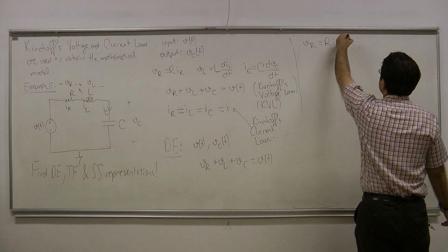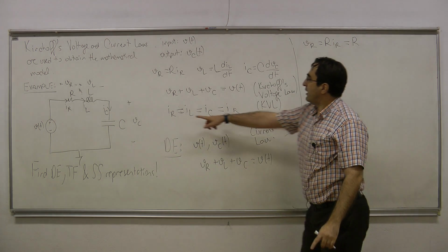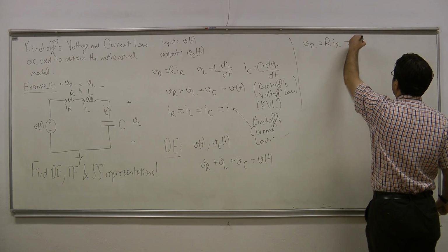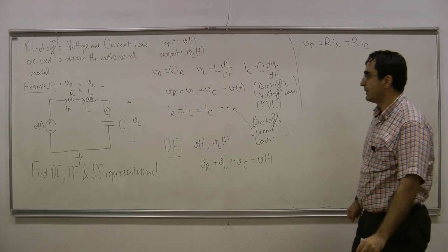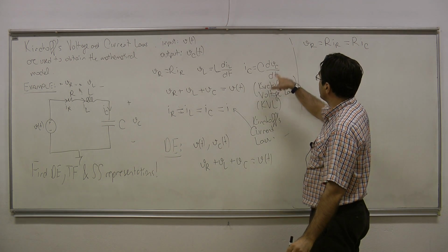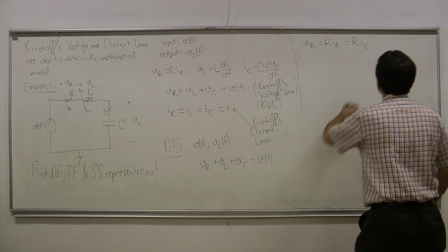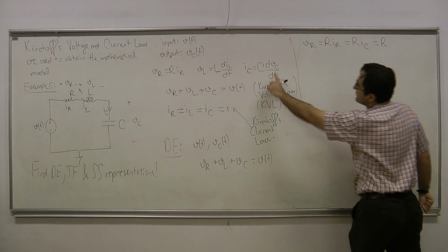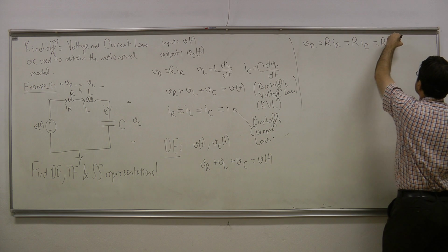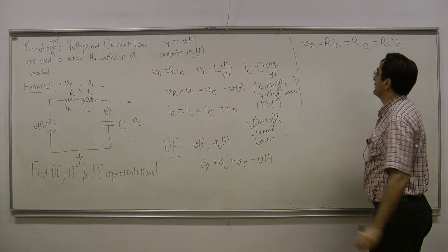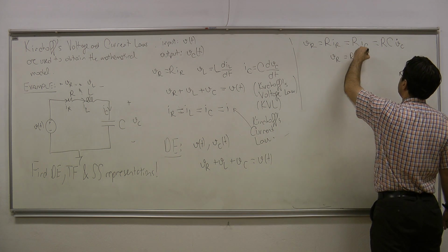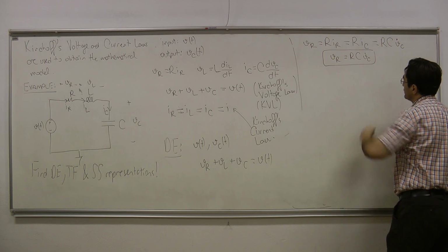The interesting thing here is that IR is equal to the capacitor current in this electric circuit. So instead of IR, I can write IC here. And what is IC? IC is C times dVC over dt. It is in terms of VC, as you see. So it is R times C times dVC over dt, which is nothing but VC dot. So I write just VC dot here. I found my relationship between VR and VC. This is RC VC dot. I'm going to be using this equation.